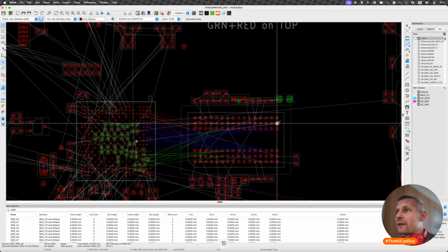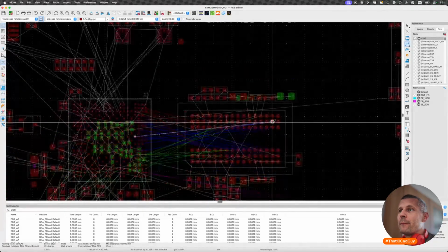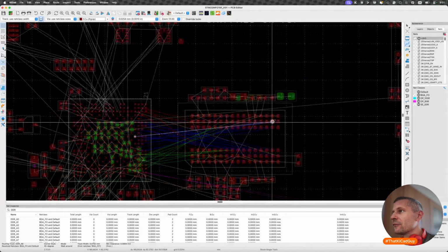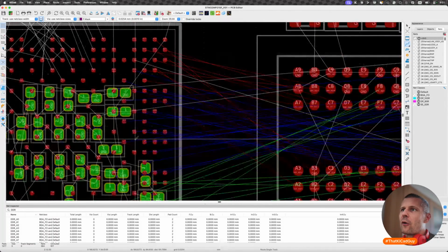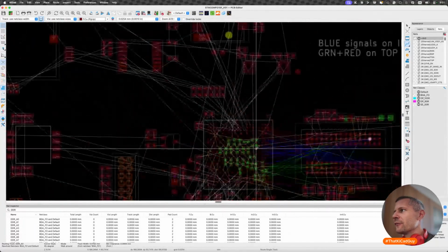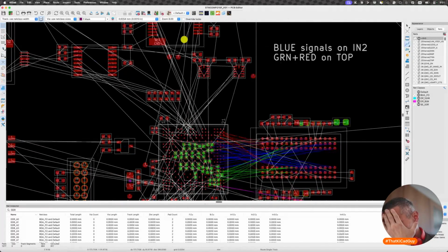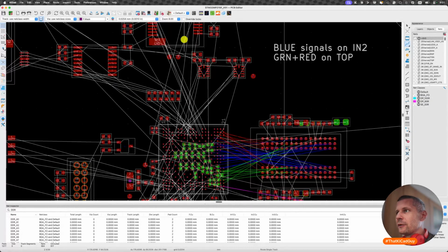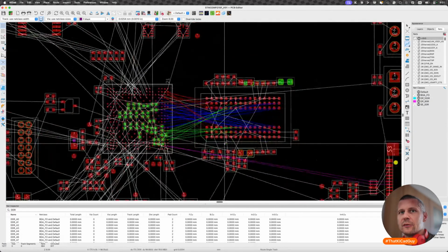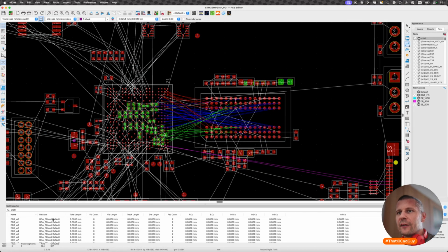Obviously, if we start with the most right path, you can see that here is the second from the right edge, and here is the 4th row. It's almost the furthest, the fifth 3 is the same length. We will see. I think it's not a first-time-right process. We will have to tune, we will have to play with it, we will have to route and delete tracks, but I think the net inspector will help us.